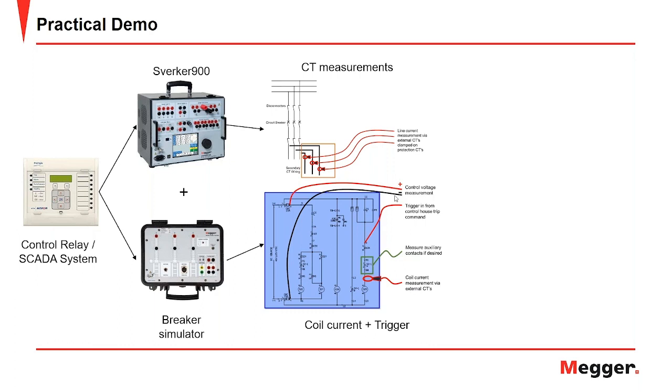As I mentioned to you, it needs to operate very, very fast. So there is a huge amount of energy. That's why you hear the bang sound when you operate the breaker. It's basically all this stored mechanical energy being released in a very short time.